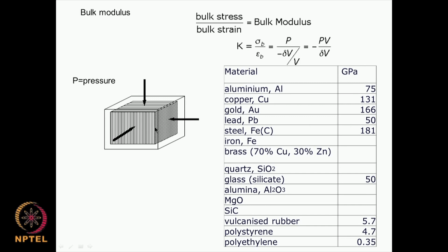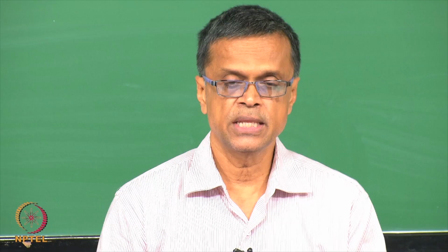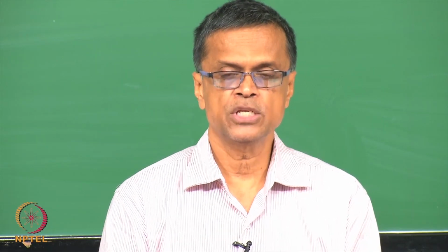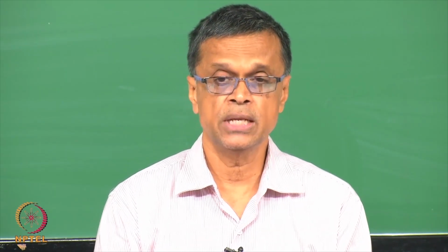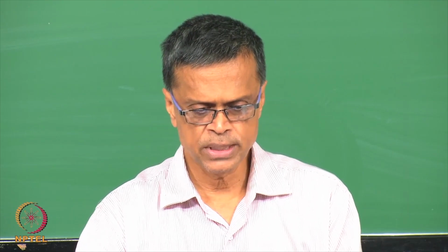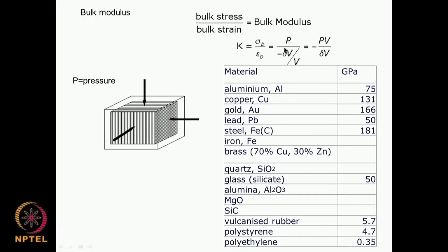So, this type of force comes into play especially when the forces are acting in all directions on the material, so that there is a change in the volume of the material, not a change in a linear direction but a change in volume, because volume is complete in all directions. In that sort of situation, for Young's modulus we put change in the length divided by original length, whereas for bulk modulus we put change in the volume divided by the original volume.